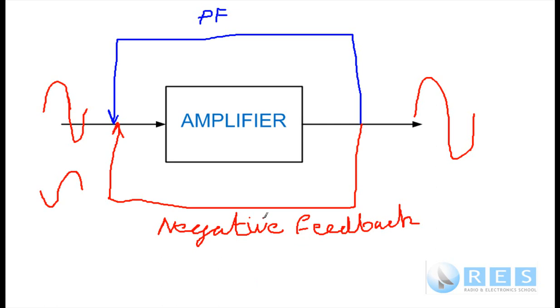In the power amplifier stage of all amateur transmitters, there is deliberate negative feedback because we do not want the power amplifier stage to oscillate, because that would mean the transmitter would transmit a signal even when the operator wasn't using the transmitter, because the power amplifier is oscillating. So in the power amplifier there's an adjustment for adjusting the amount of negative feedback to cancel out the unwanted feedback. And when we use negative feedback to cancel out unwanted positive feedback, we call it neutralization. And it's a pretty appropriate word if you think about it.